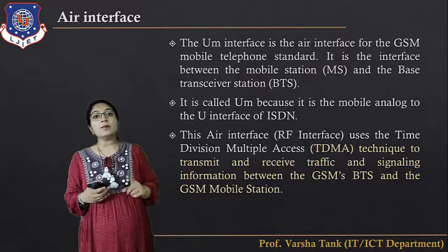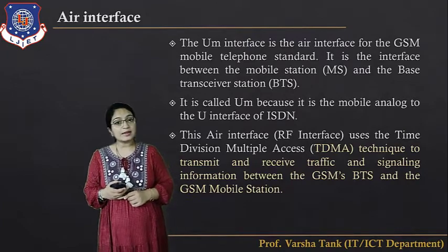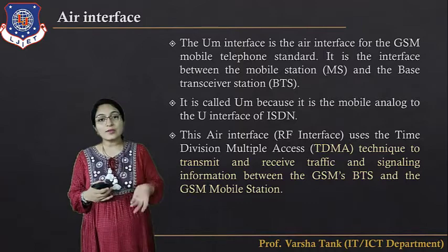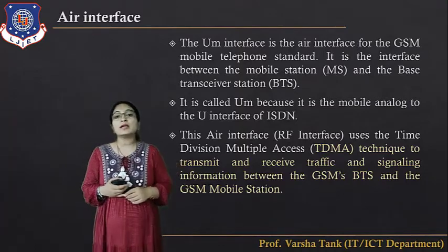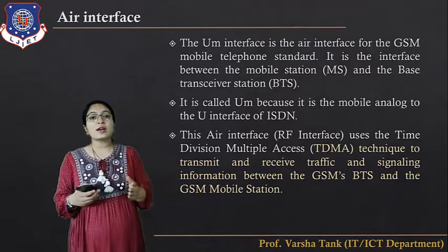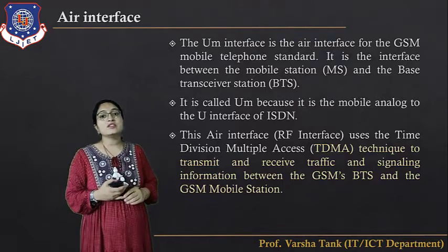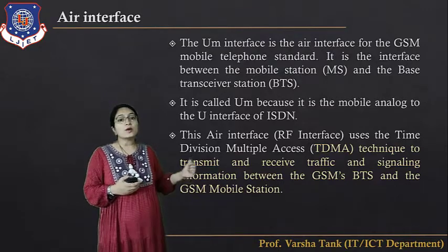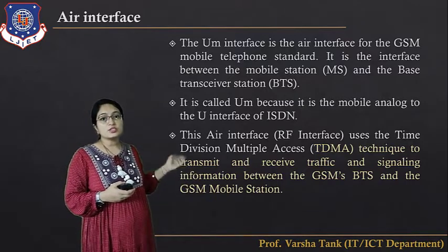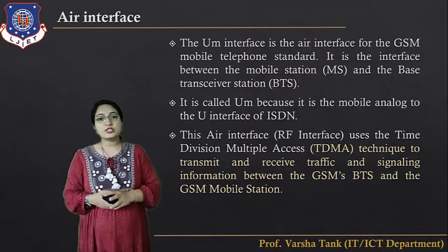It is called the Um because it is the mobile analog to the U interface of the ISDN, that is Integrated Service Digital Network. So this air interface or RF interface uses the time division multiple access technique, that is TDMA, to transmit and receive the traffic and signaling information between the GSM BTS, that is the base transceiver station, and the mobile station.